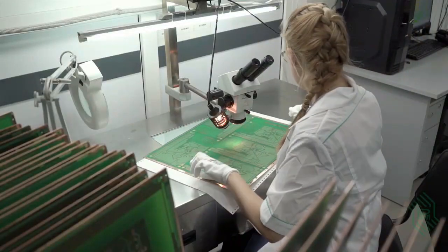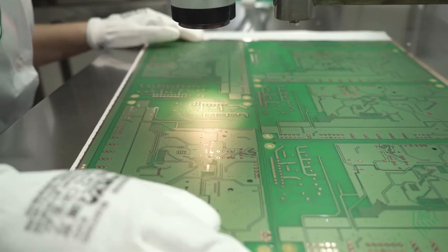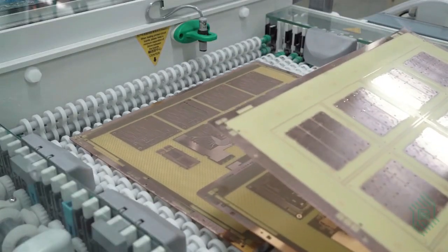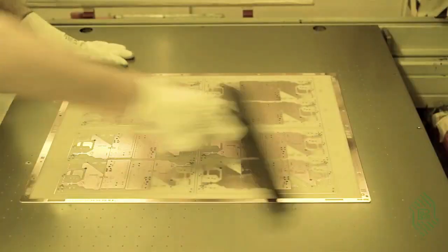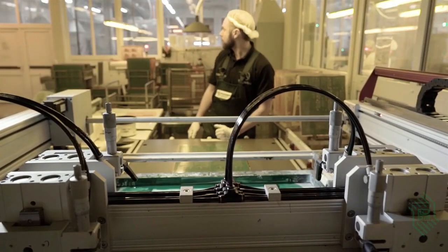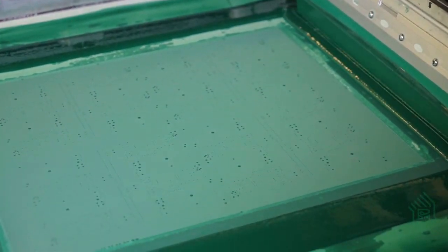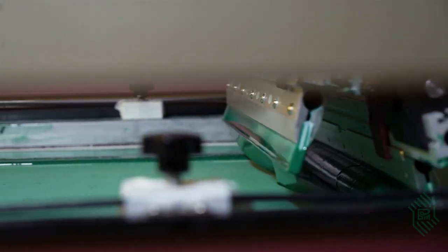In this stage, the solder mask is applied, the mask openings on soldering points are formed, and the final curing of the mask layers occurs. Before applying the mask, the copper surface is cleaned, then the necessary roughness is developed for the good adhesion of the solder mask. Liquid solder mask is pressed with a squeegee through a screen over the entire surface of the panel on the screen printer. For double-sided PCBs, the process is repeated.